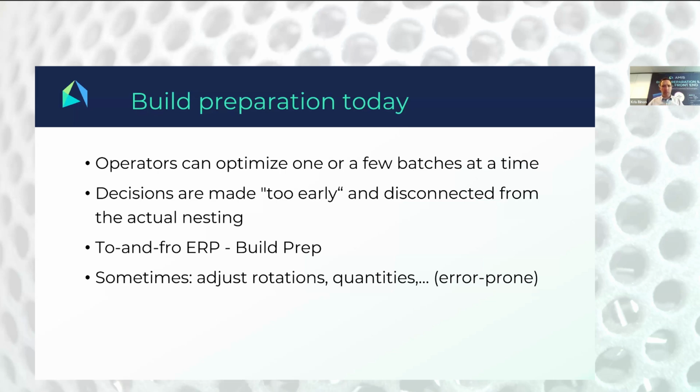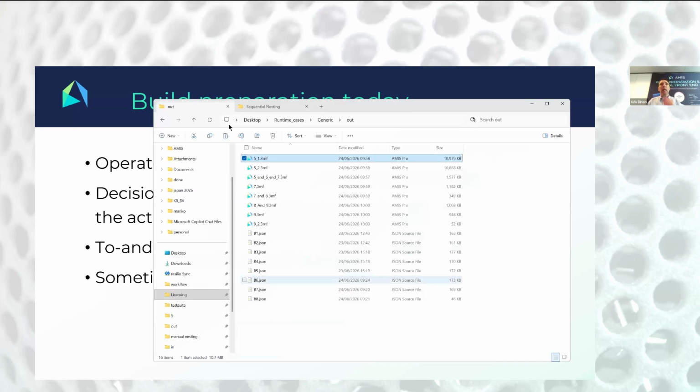Whereas, and we also noticed that here in the overview, by the way, my parts for the 5th fitted in 2.5 batches, because in the third one I could already add parts for the 6th and the 7th, which is great, of course, but it might have been much smarter to actually divide those parts for the 6th and the 7th over the 3 batches equally, because maybe there were smaller parts that nicely fitted in the bigger parts, so that you automatically come to a much better density, or a more even density throughout your batches, meaning also, of course, lowering your overall need for batches.